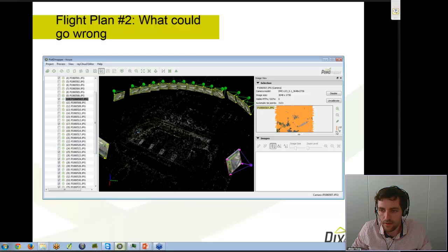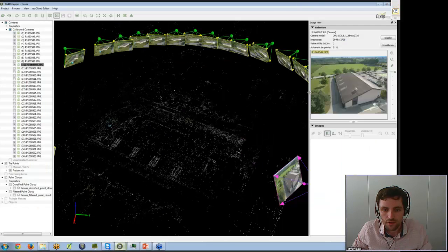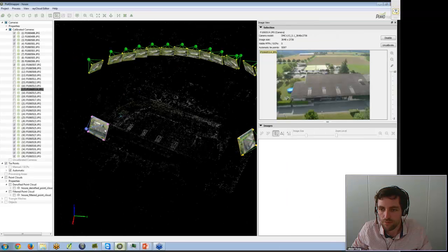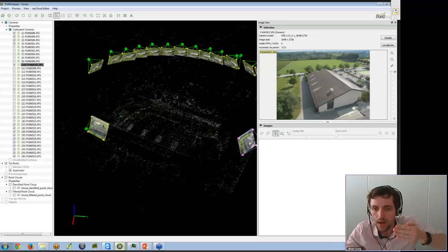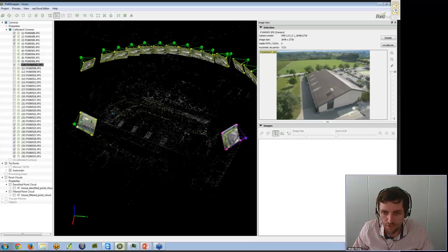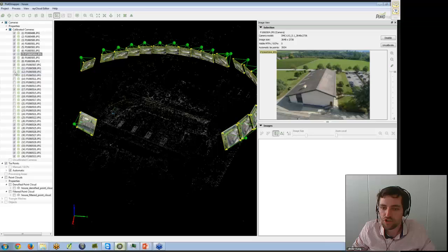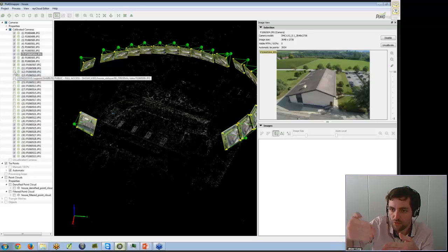And if you look at the content of the images, the software would very likely not be able to match content from this image with an image which is taken at almost 90 degrees from it. However, the trick to make it perfectly work is to have images in between. By having images in between, the software is able to track much better one feature across multiple images.